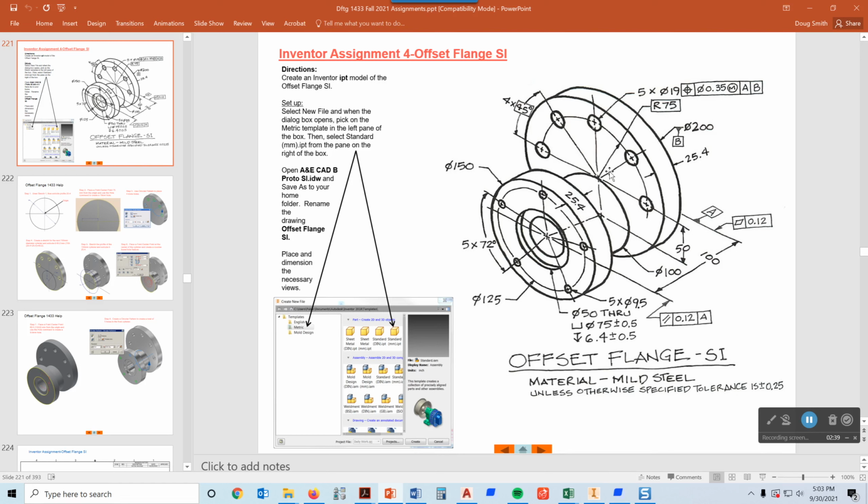So measuring from the center axis of this cylinder, we come out a basic 75 millimeters to find that arc right there. And then we also, relative to where the center axis is, we have 4 perfectly 45-degree angles. And what that does is locate the 0.35 cylindrical tolerance zone. And the center axis of all of these diameter 19 holes needs to run right down through the center or stay within that 0.35 millimeter cylindrical tolerance zone.